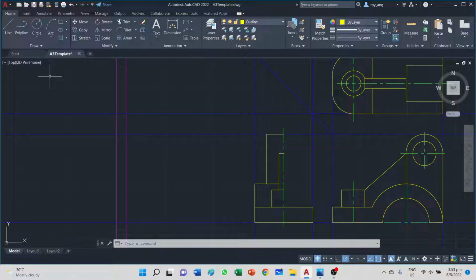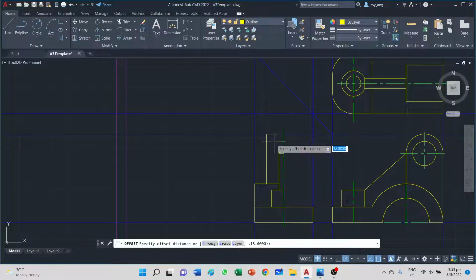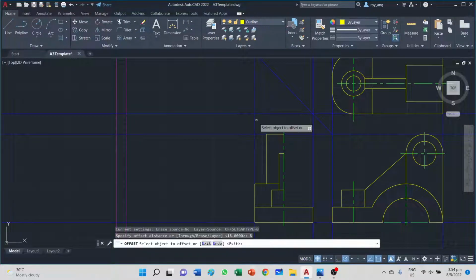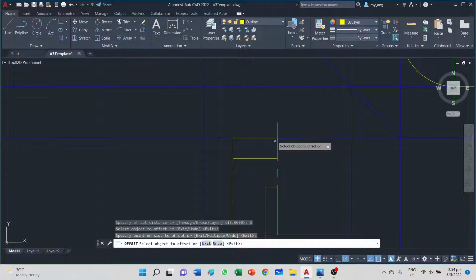This is the outline that you have, and guess what? We can draw the cutout from here. And we know that there is an offset. It's cut out 8 millimeters from the top. So 8 millimeters from the top. If you look at this, this is the one on the top. The cutout is 8 millimeters from top and 12 millimeters in the center. Sorry, 6 millimeters from the center. So I'll do an 8 millimeter offset first. That's a fairly deep cut.